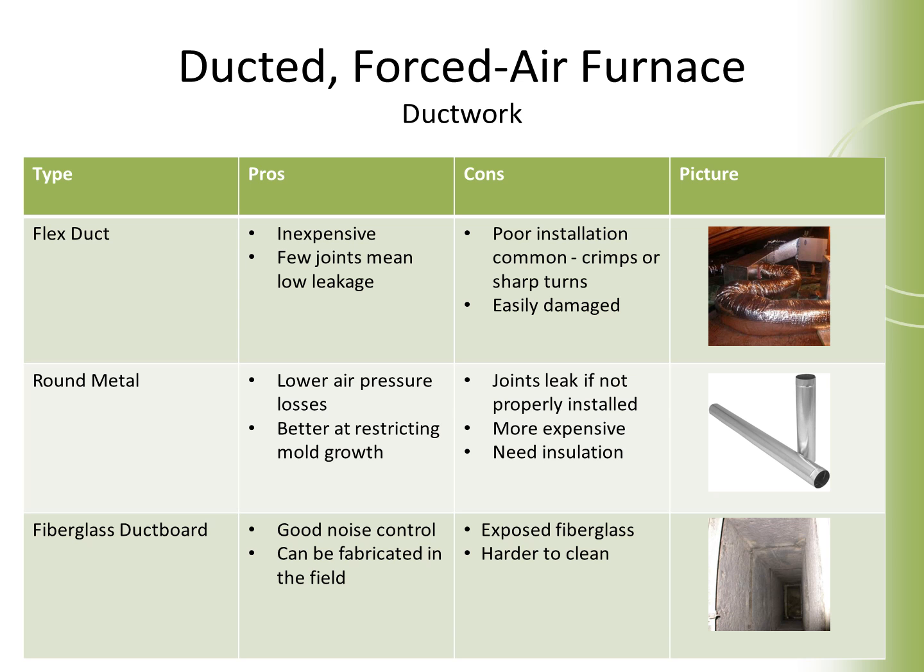Fiberglass duct has some positives. It has good noise control, and it can be cut and fabricated fairly easily in the field and usually taped together with actual duct tape. These can have exposed fiberglass and can be harder to clean, but they do have fairly good insulation value.